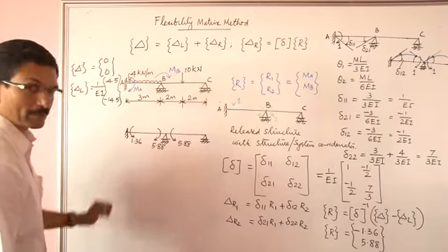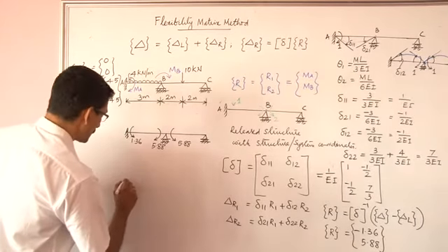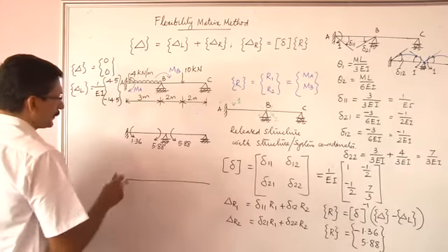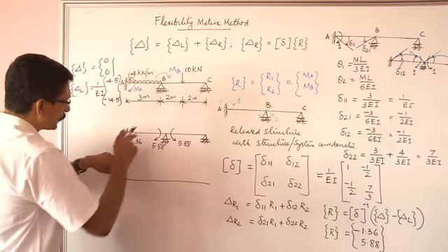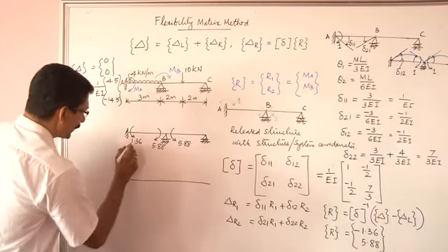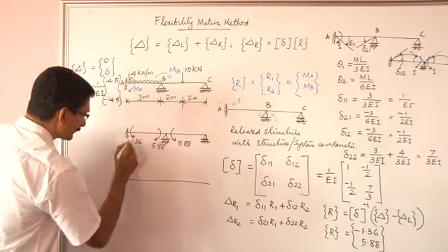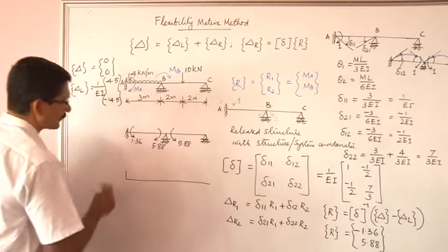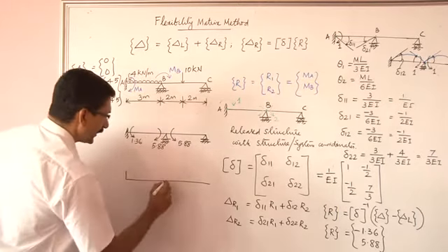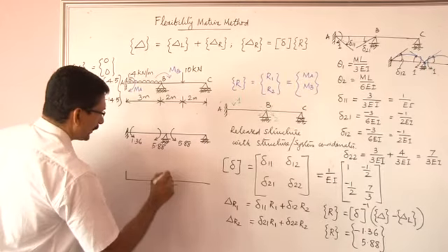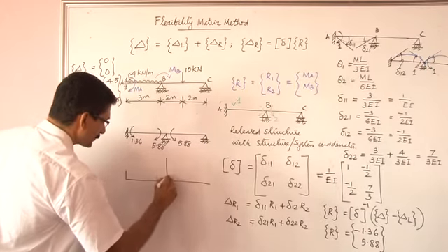And finally, if you draw the bending moment diagram, we have 1.36 is anti-clockwise. We can draw this ordinate towards the tail end of the arrow mark like that. And these ordinates again to the tail end of the arrow mark. So this is 5.88.